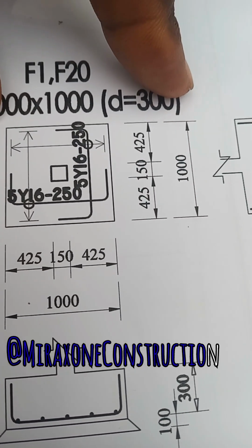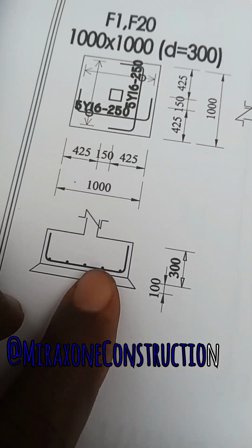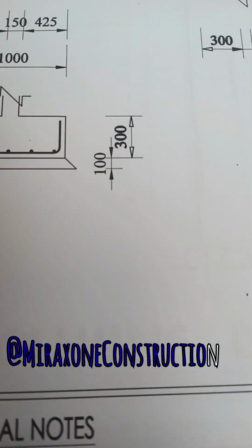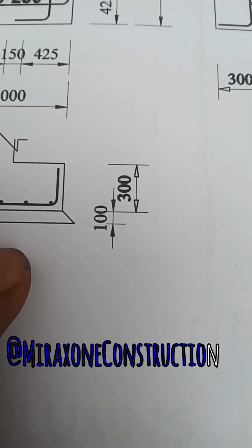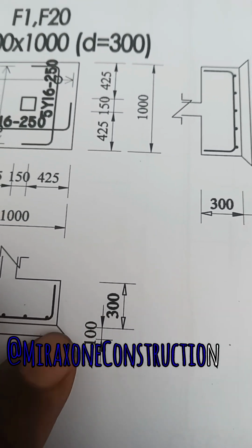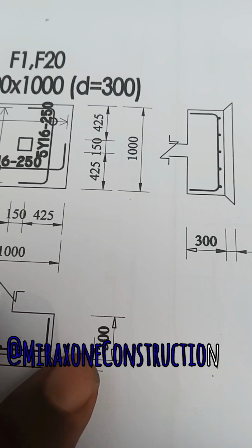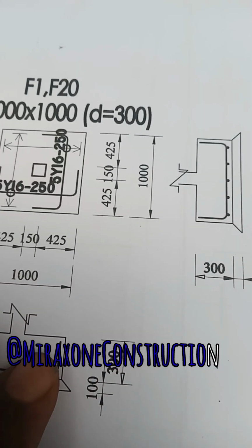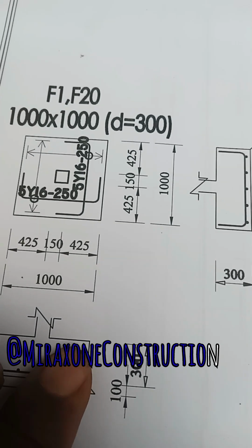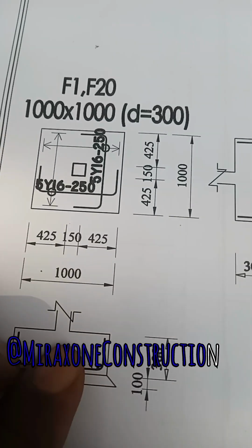I hope you understand. This particular one you are seeing here is the plan. This 100 here is the concrete cover. The 300 here is the depth. This is the hook, just like I have said before, of the footing reinforcement. This is how it's going to look.